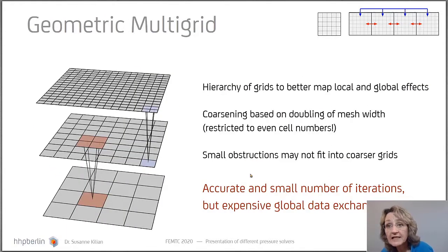And this is the reason that I also implemented another solver, which is based on the well-known multigrid methods. These methods do not only use the original fine grid, but also a sequence of at least one or even more grid levels, which are getting coarser and coarser. The idea behind it is to be able to compute the basic global information, at least in a coarse sense, with fewer grid cells and less effort, to finally get a much better global coupling of the overall problem.